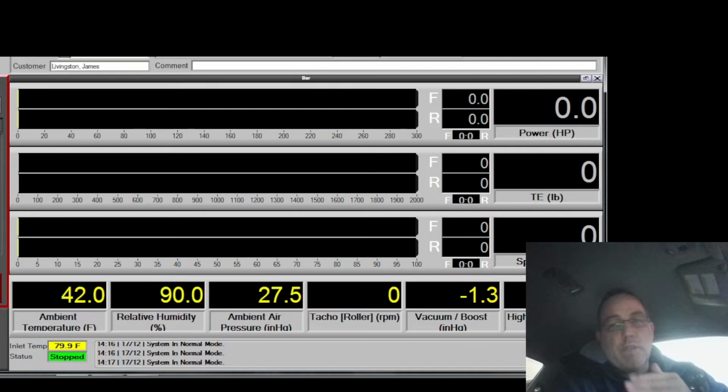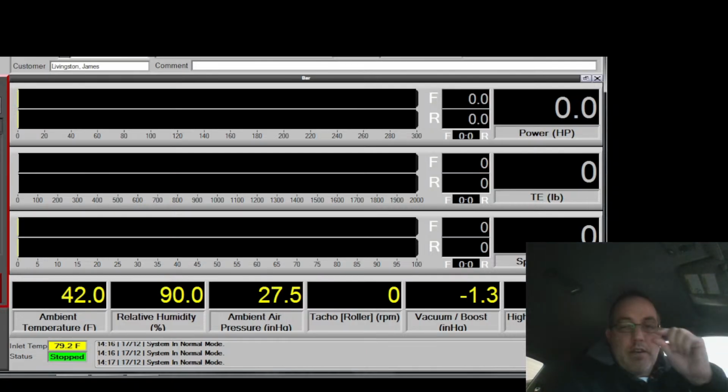The potential difference between those two electrodes is so high that one side will strip electrons off of the atoms in between those two points, and then that movement of electrons creates current flow. Now, in order to do that, you have to have enough spark energy, and we rate ignition coils in millijoules. It has to have enough energy, make it to the plug, to ionize the molecules between those two electrodes.